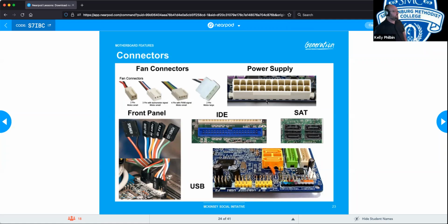Right here, you have your PS1 or 20+4 connector, which is your main power supply connection, so that's going to be one of the biggest connectors sitting on the motherboard. Over here, you have some fan connectors, like little 2-pin, 3-pin, 4-pin. And then you have the IDE connectors right here, which are for old-school floppy drives and hard drives and things of that nature. These are the older connections.